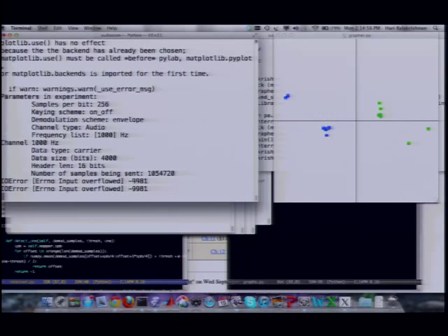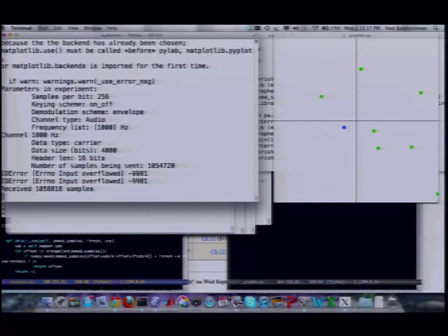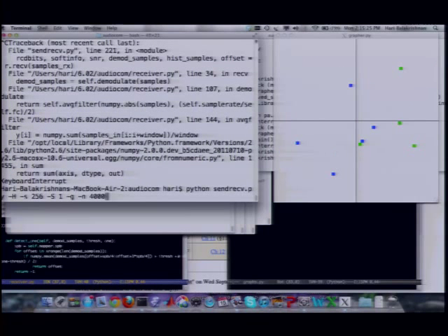You can see that what's going on here is, if I'm silent, the points get demodulated at +1 and -1 that correspond to the top and the bottom of the waveform. And if I make a noise, the effects of noise get visible. In fact, you can see that sometimes the points on the left go to the right and vice versa. Okay? So that's a very visual effect of what noise does to your transmission. I'm going to do this again so you can see what's going on.